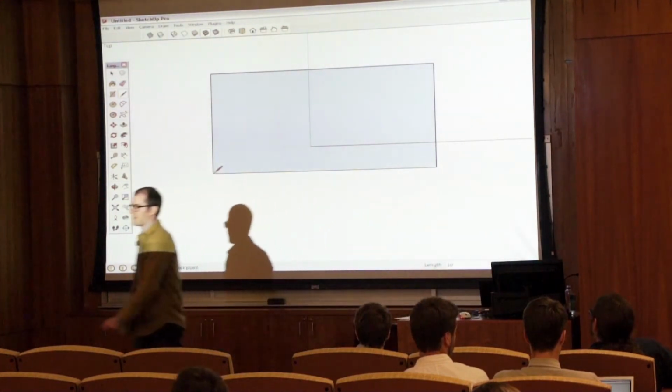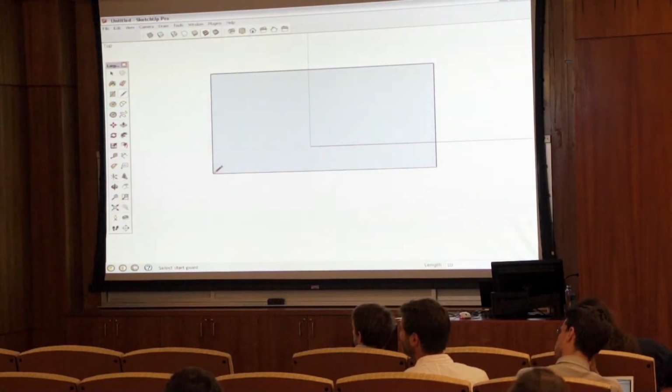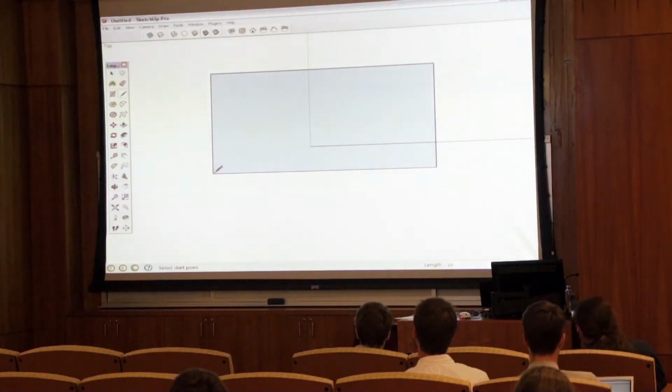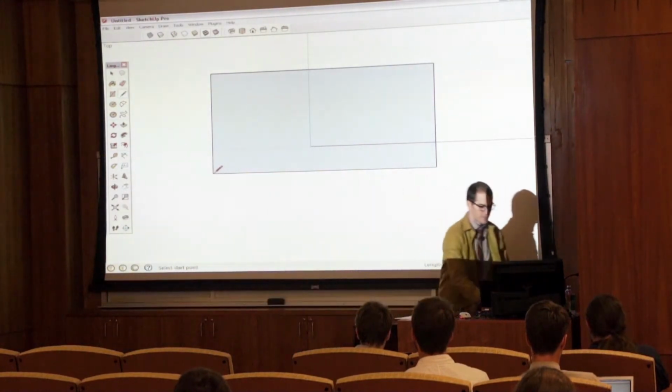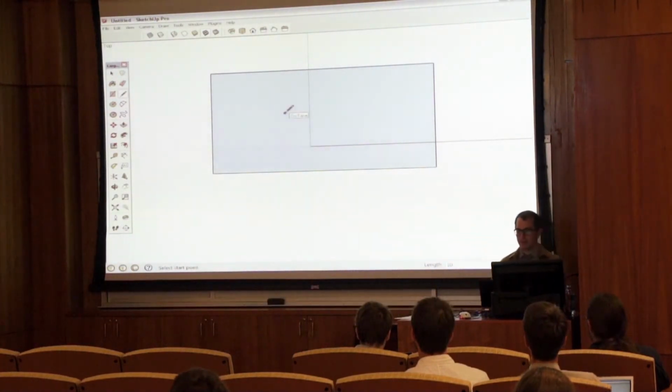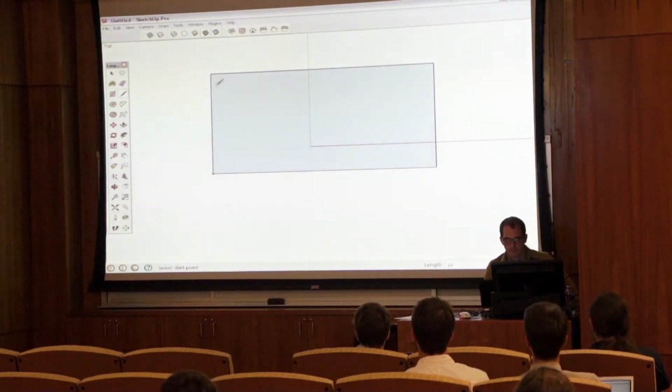Last but not least, you can draw a line and basically close the loop. And that way it creates a surface. Now, SketchUp refers to surfaces as faces, and it refers to lines that make up a surface or face as edges. So go ahead and just hover your cursor with the line tool over some of those edges, and you'll see a couple color changes in the model. For example, as I hover my cursor over a face, see how the cursor point turns to a blue diamond? You'll notice at an endpoint, it's a green circle.